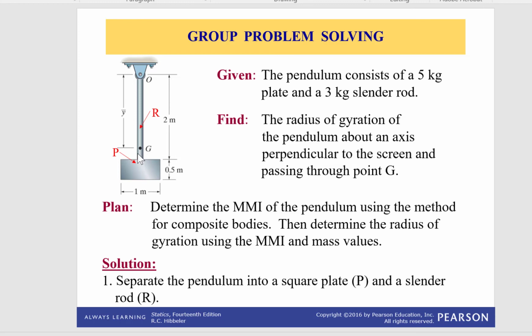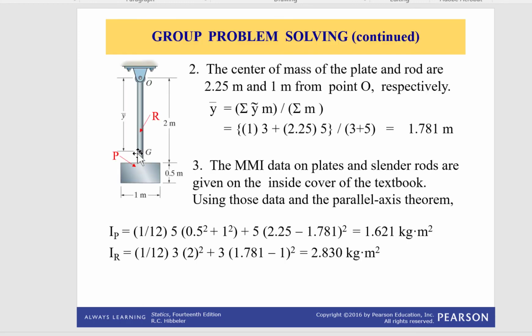which is equal to the total mass multiplied by the location of the centroid for all of that. So this goes back to this formula, and I think you are all familiar with that method of determining the centroid of areas, volumes, objects, masses. That's how it should be calculated, and that will be 7.81. Now the problem here is asking how much is the mass moment of inertia for an axis passing through that point G, not through O.